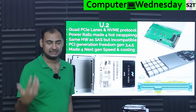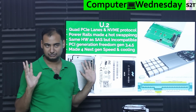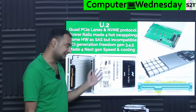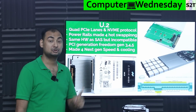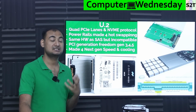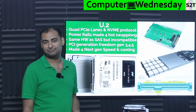And it also saves them because they are using the same form factor as 2.5-inch hard drives. So no new caddy design. Basically, server people are very slow to change. They're like, what if we can just Control-C, Control-V this? They Control-C, Control-V this, but it was made for next generation speed and cooling. That's why all the SSDs made for server grade and U.2 have such a chonky feel to them, because they're designed for heavy use. It's not like M.2, where cooling is barely needed.